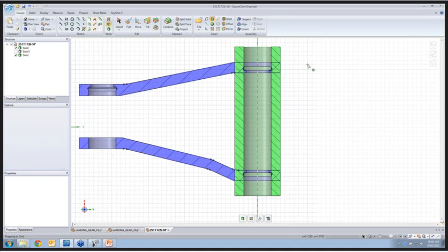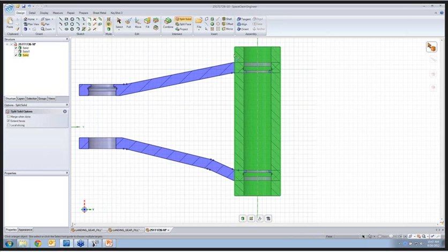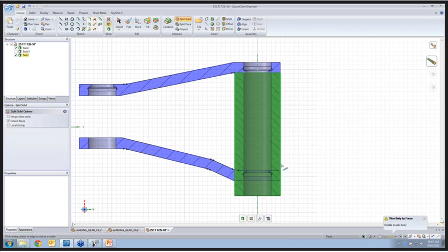Now, I obviously need to take care of the interference problem. I could have made this the correct size right away, but I did it this way because sometimes it's just easier to get something on the screen and then use the fast tools in SpaceClaim to chop up a model however you want. I'm using a variation of this fourth tool called Combine. It stands for combination. It cuts bodies, but it also merges them. So I'm using it to slice this body along key locations. And so now the fit is much better. The pin pretty much looks the way I want it.